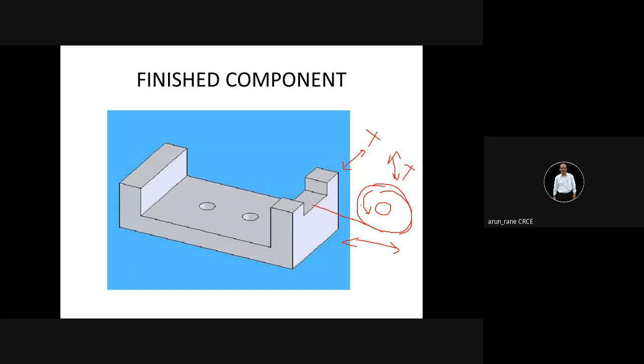So in the z axis also we set the cutter, that is this. Here we place a setting block. This is called the setting block, which is kept on the table. This is the table, and on this setting block we set the milling cutter. And then once the component is loaded, we simply move the cutter in longitudinal direction.